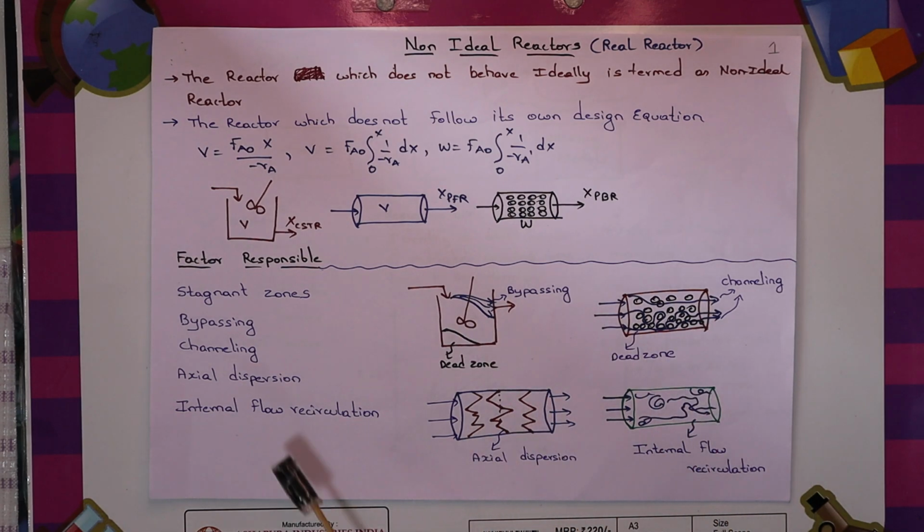What is axial dispersion? When the reactant molecules are entering the reactor, there is a special term called dispersion or diffusion. That means once the reactants enter any reactor, because of diffusion, there is a possibility it might go back, it might go further. Diffusion means the molecules of A can diffuse even backwards and forwards because of the concentration gradients.